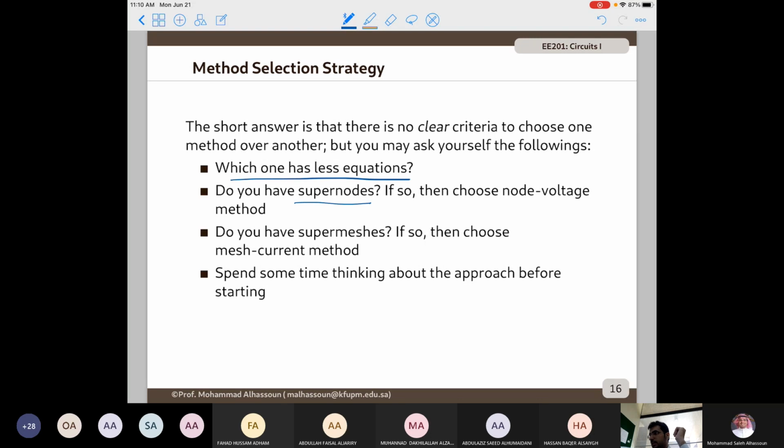Let's analyze this issue with the following circuit. Ziad? When it says a voltage or a current source, do they mean an independent one, or does it not matter, and if it's dependent, we just add one equation? It doesn't matter whether it's independent or dependent, because in either case, you know the value.